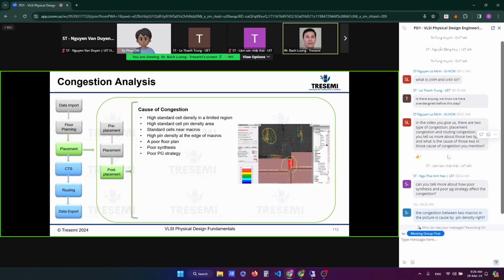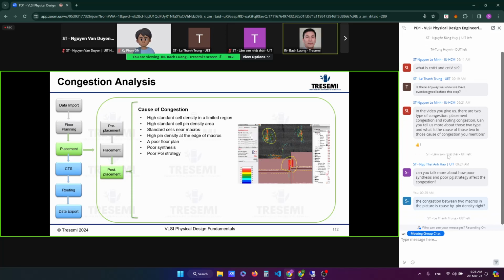I think in the lab, if you've done lab two, you see that after placement the timing gap can be a huge difference, 20% or depending on the design and the technology. You assume it's not going to be 20%, maybe 10% or 5%, but you end up at 20% or 30% difference, right?